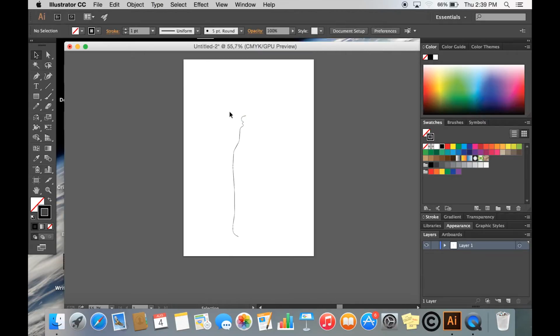What you'll do next is copy the outline of the side of your bottle by holding in Command, pressing C and then F. Next, select the reflect tool, shortcut here is O, adjust the anchor point, hold down Shift and then flip the bottle so that you have an equal proportioned other side. After this, you can select the entire object and center it once again.